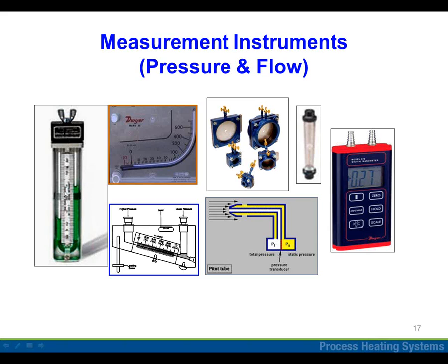You've got to be at least 40 or 50 years old to know how to use the manometer, because today's generation would use a digital manometer, which is diametrically opposite. But remember, even those instruments need to be calibrated. And the only way you're going to be able to calibrate that is to use the old-fashioned manometer. So we bring manometers as well as digital instruments for measuring the pressures and flows, particularly pressures, delta P also. The one on the top left side middle is an inclined tube manometer that is used for draft measurements.